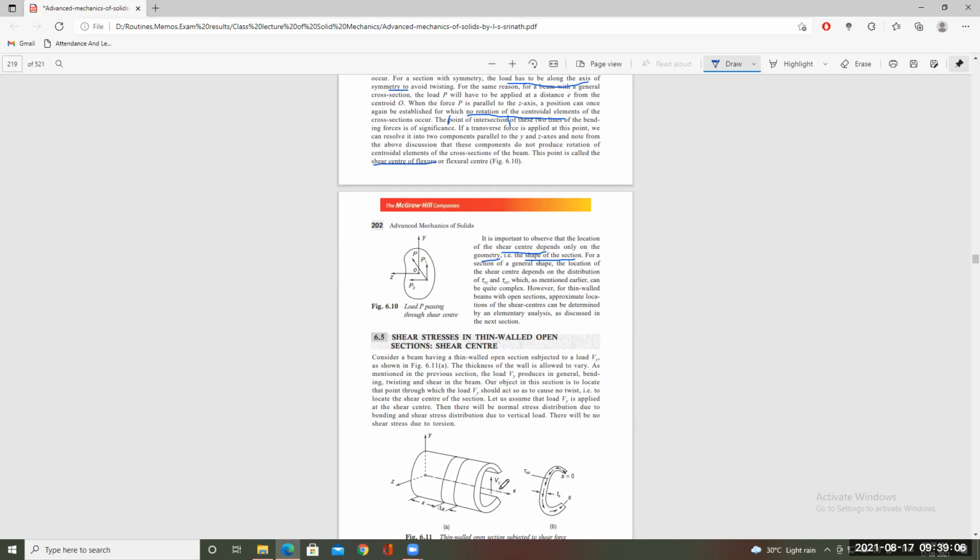And we are having a force equal to Vy, which is vertical in nature and parallel to the y-axis, but away from it. Now, what will the load Vy produce? Bending, first of all, no problem. This end is embedded in the wall itself, and if you apply load, it will bend. And it is away from the CG, so it causes twist of the beam and shear. There is also shear or vertical stress existing in all the cross sections of the beam itself.